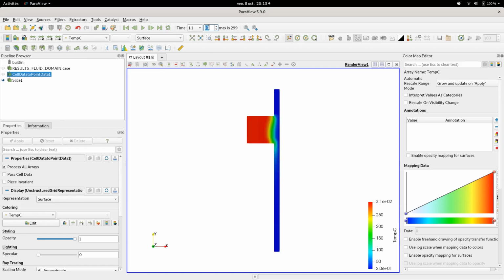Please keep in mind that all iterations between the first iteration up to the steady solution are not physical. It gives you results regarding the simulation. So, for instance, you can change it to 50, and you can see the results evolving.